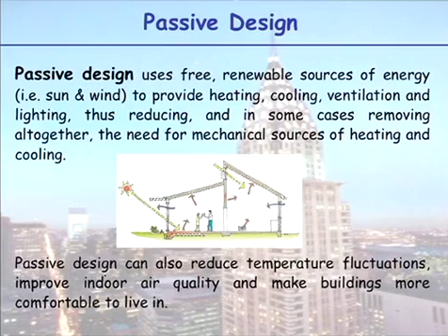Passive design uses free, renewable sources of energy, i.e. the sun and the wind, to provide heating, cooling, ventilation and lighting, thus reducing, and in some cases removing altogether, the need for mechanical sources of heating and cooling. Passive design basically is the way they used to live in the old days, where they didn't have the option of turning the aircon on, so they thought much better about their designs.